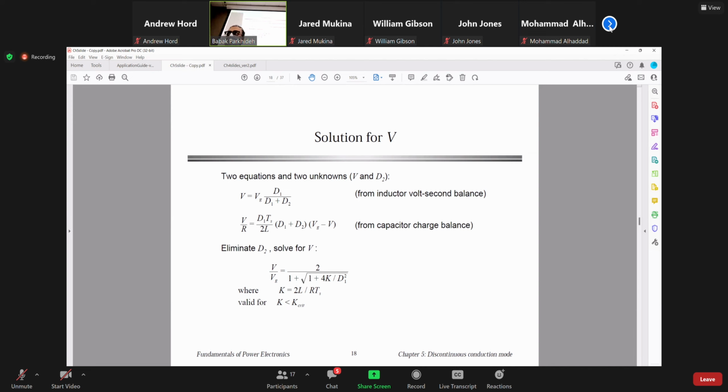Again, it gets even more complicated. As you can see, with non-ideal converters, the characteristics of a converter under the continuous conduction mode that I showed by simulation now have a relationship that depends on circuit parameters other than duty cycle. Now, L, load, and switching frequency affect the characteristics. And with the K term that we defined, now we can simplify this.